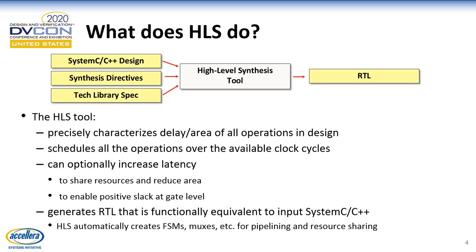And one of the differences between high-level synthesis and RTL synthesis is that it can add clock cycles into your design if you allow it to, and it can push operations across clock cycles. It can also do things like, if you have memory accesses, memory reads and writes, it can schedule the memory read and write operations across different clock cycles. These are the activities that typically RTL designers need to do.